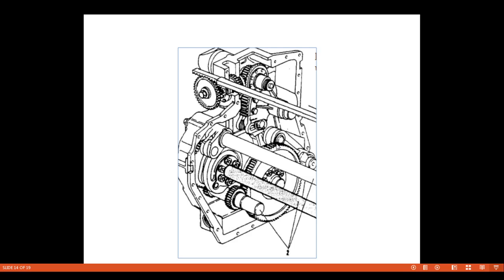So what will happen, the stroke cam lever moves up and down one time. That's why the segment gear moves one time up and down, this gear will move clockwise, anti-clockwise, and here the bevel is given which moves clockwise, anti-clockwise. So this pinion will move clockwise and anti-clockwise.